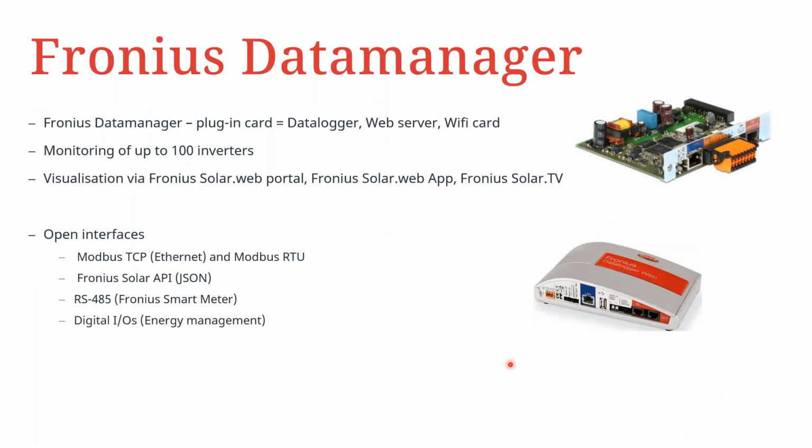Let's delve deeper into the data manager now. The Fronius Data Manager is basically a plugin card that performs the function of a data logger, a web server, and of course has a Wi-Fi card integrated into it. So it's basically a PC board that has all these functions as listed. It has the capacity of monitoring up to 100 inverters.